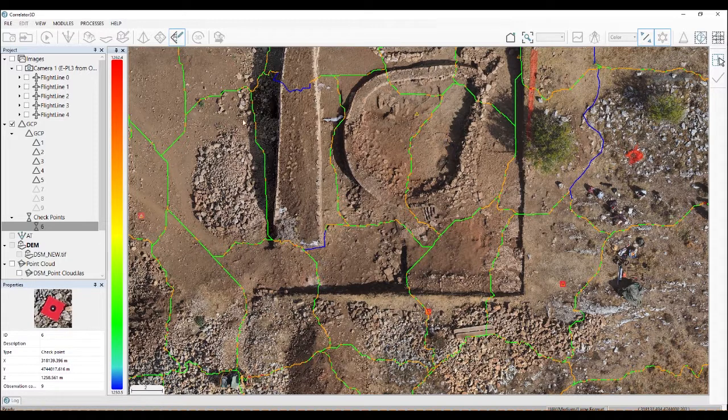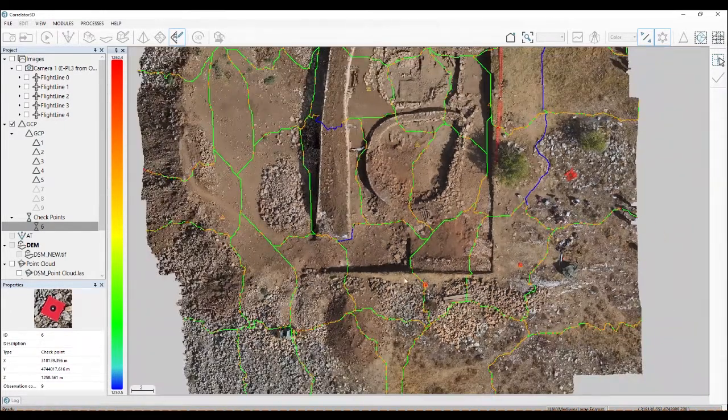Usually the seam line algorithm is very good to already go in places where it will not be apparent, but if you are in a very dense urban area, that might need a little bit of editing, and that's really how you can get a much higher quality product to deliver to your customer. So because you have this option to edit all the seam lines within Correlator3D. Once it's done, you save this, and then you can just export the mosaic with the applied changes.